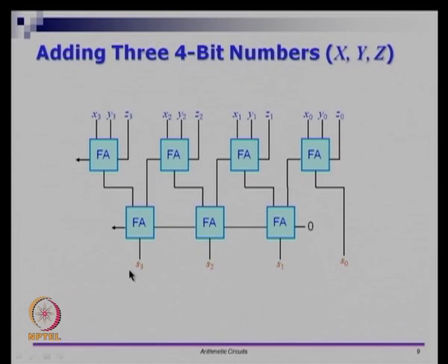So instead of one complete ripple carry and whatnot, we have used 2 full adder delays, and with that you can actually get addition done. So 1 plus 3 is 4, actually you need 4 full adder delays in the worst case. So 3 numbers can be added together, instead of incurring a ripple carry of n minus 1 plus another ripple carry of n minus 1, we can actually do it in 4 steps here.